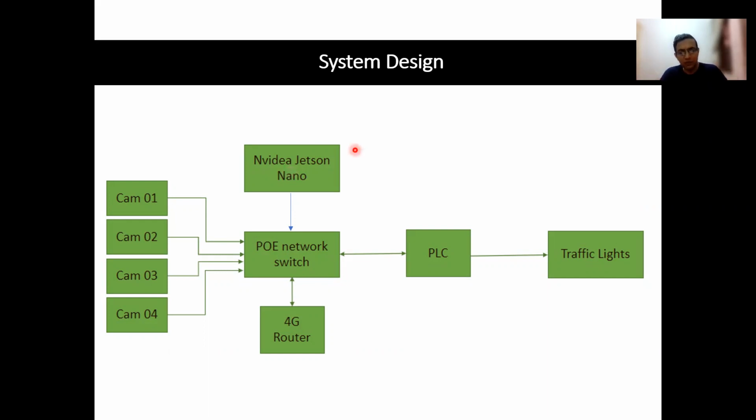Now what about the cycle time? Is it the optimal cycle time? I don't think so. But unless we have a certain way to calculate the optimal cycle time, we should not change it at this moment. So you keep the cycle time unchanged and do the adaptive timing within the cycle time. Phase times are adjusted, not the cycle time. But when you look at the broad picture, looking at the nearby junctions, you can set the most appropriate cycle time for the junction.